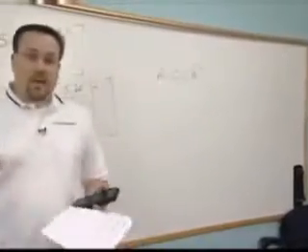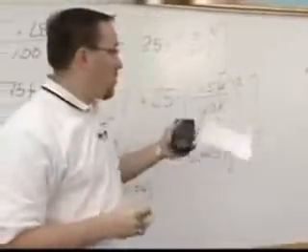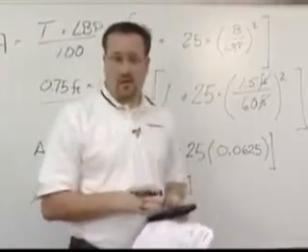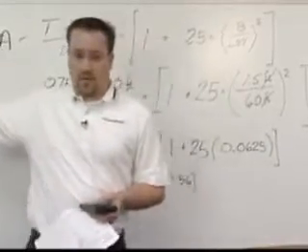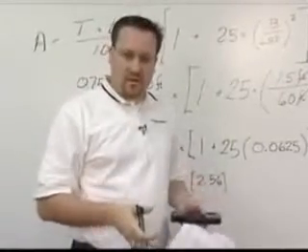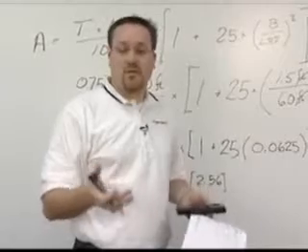As I mentioned, this is probably a lower limit, and that's a pretty small area of rudder. That's about 3 inches by 3 inches, a little bit bigger than that, for a boat that's 6 feet long. Okay? We're going to do this calculation again using the other method that's included in the guidelines, and you'll see that the answer is going to be somewhat larger.